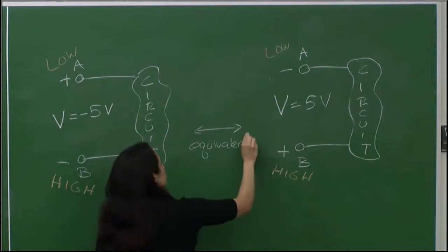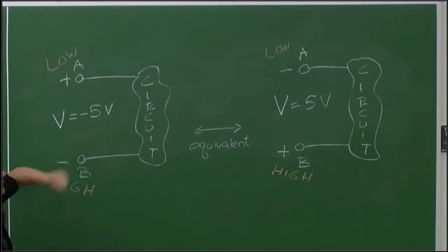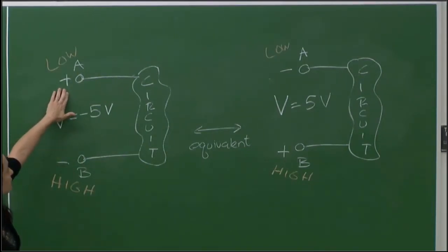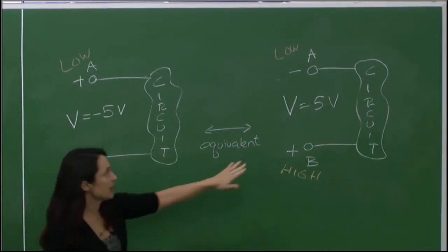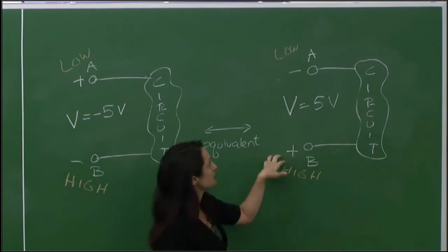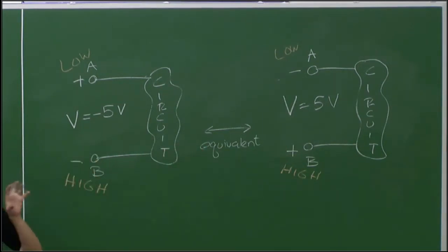So what I want you to start to get a feel for is voltage change across 2 points is the potential to move current around. What does it mean when you have a negative reading? Well, it's really the potential is the other way to move things. And even if this was designated as a positive terminal, he's really at the lower potential due to this negative reading. Positive reading, it's really how these guys are tagged and which way the current will then flow, and then what happens to those coulombs as they go through there.